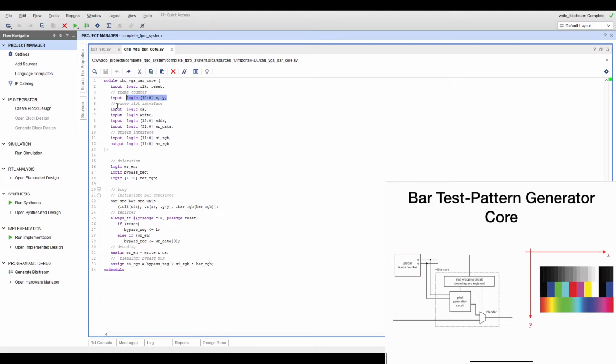And the standard video slot interface that we need is actually the chip select. The chip select is the one that basically tells me this is the core that the video controller decided that the processor wants to communicate with. Because remember, we have 8 of them, and usually they're connected to some sort of a decoder. Okay, and then there's the write signal, which basically is distributed.